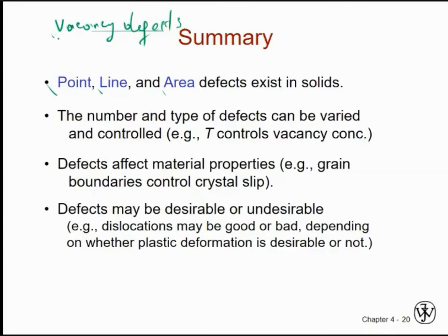If I want to make a material electrically conductive, I can add some other element which is electrically conductive to the previous one and increase its conductivity. Or let's say I can add carbon to iron. It will be an interstitial solution, and I can increase strength of iron, but it will be more brittle as I add carbon, but stronger. As a result, we are manipulating properties.